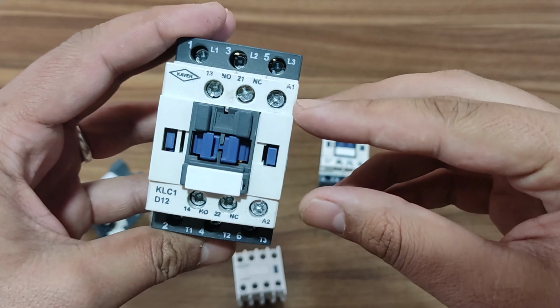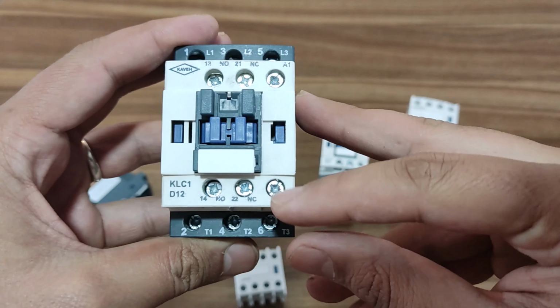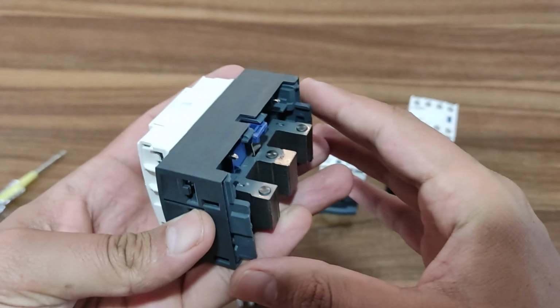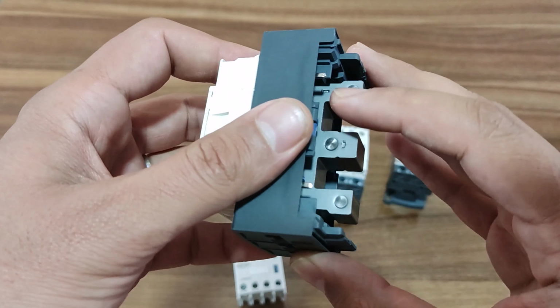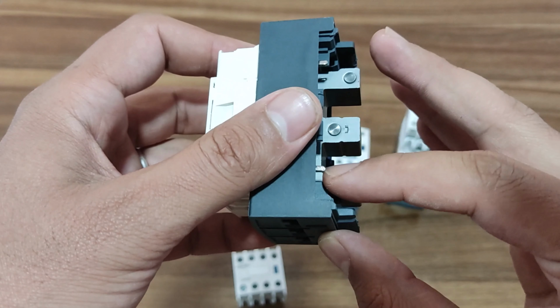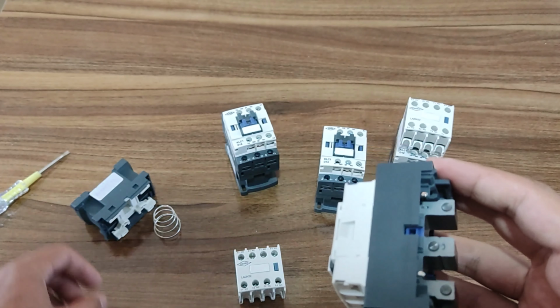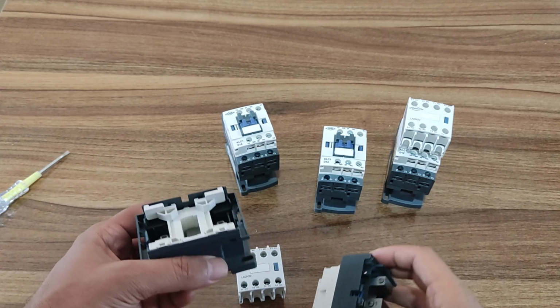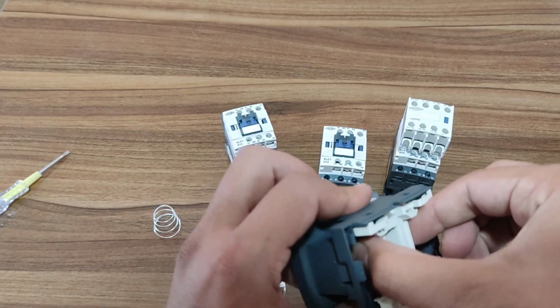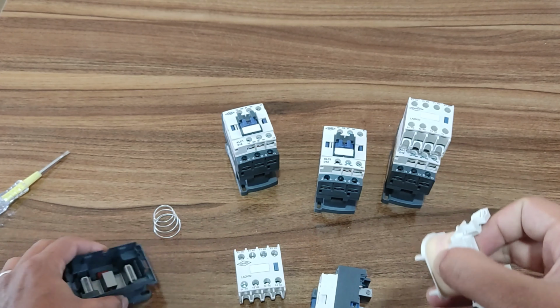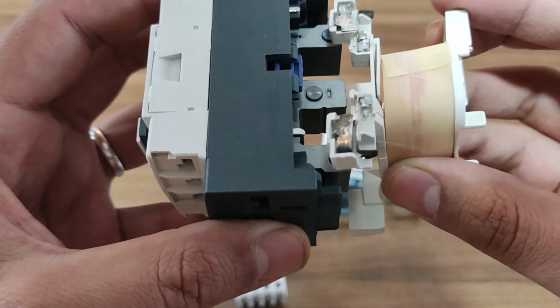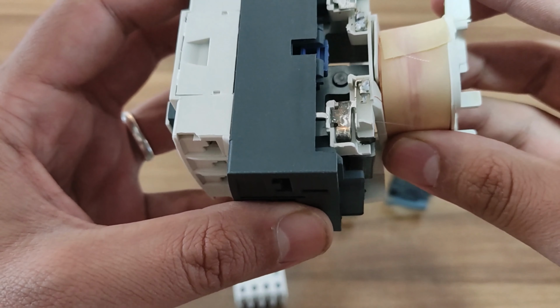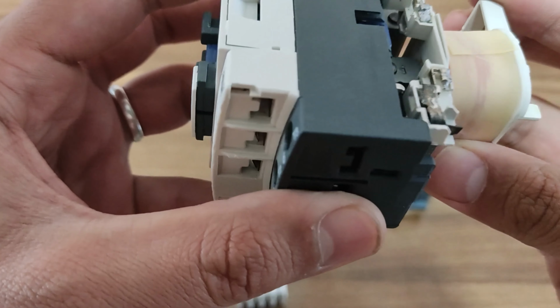Today, contactors may be designed for specific purposes. One of these purposes is the connection of capacitors. When connecting the capacitors to the circuit, a large inrush current is drawn from the network, which can reach 100 times the rated current of the capacitor. This current has a high frequency of about 3 to 15 kHz and it exists for a time of about a few milliseconds and then it fades.